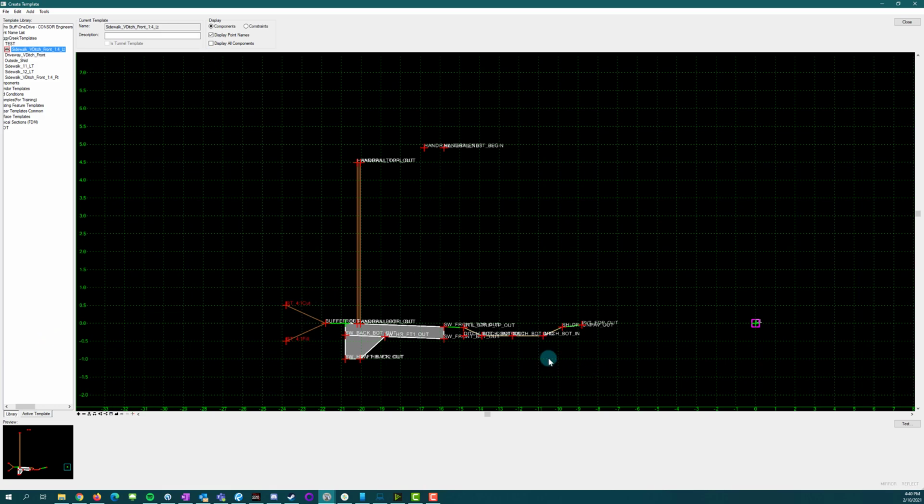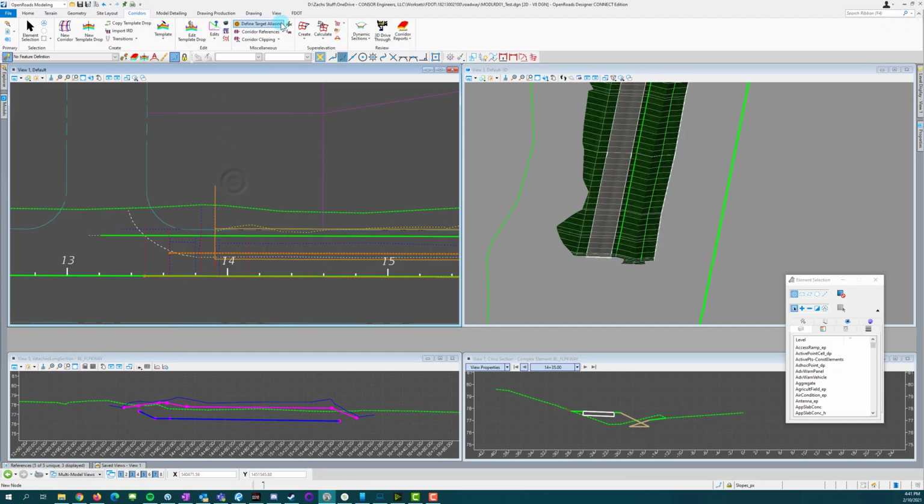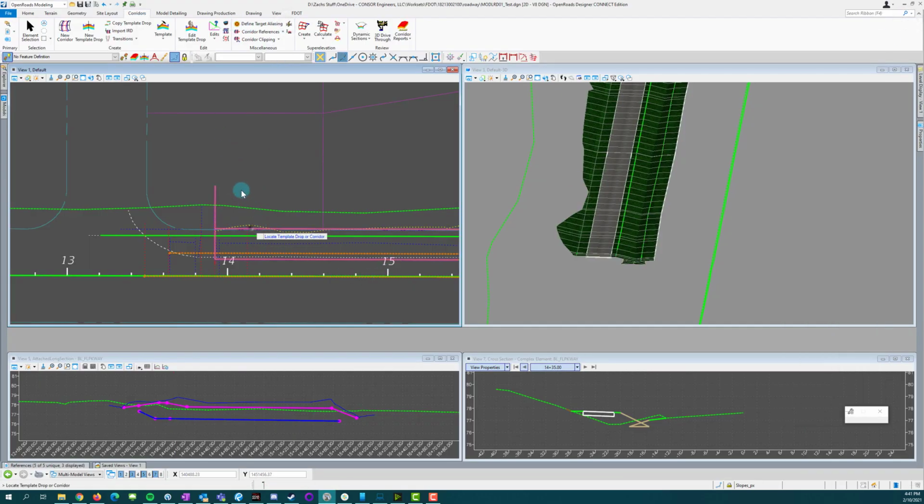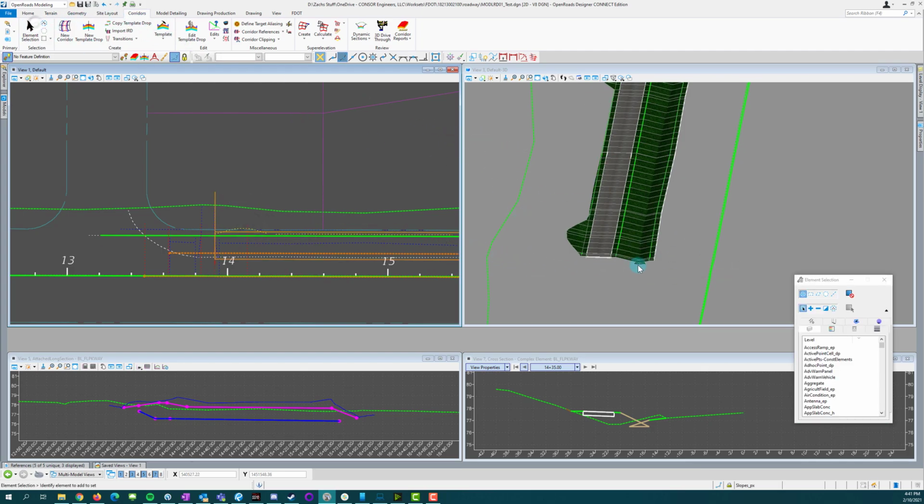Those are situations I've had too, where I have an end wall and I have to handle that. So I try and have this 2-foot flat to the back face of my end wall, so that I make sure I have the full 2 feet before I even hit that wall. And then I don't need to worry about that drop-off condition. So we've tried to minimize this as much as possible, so let's hit save. And we need to update the template. So we're getting closer.